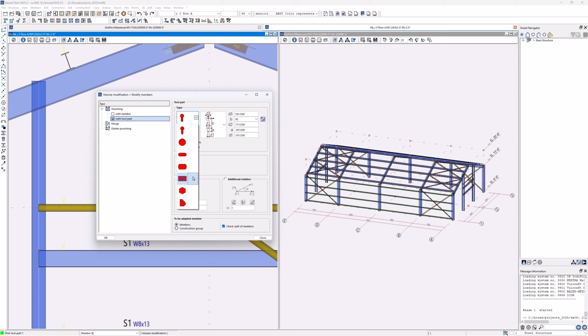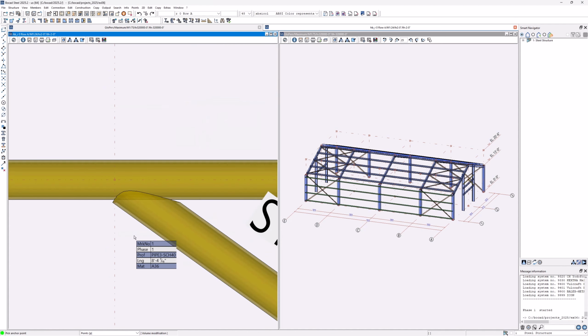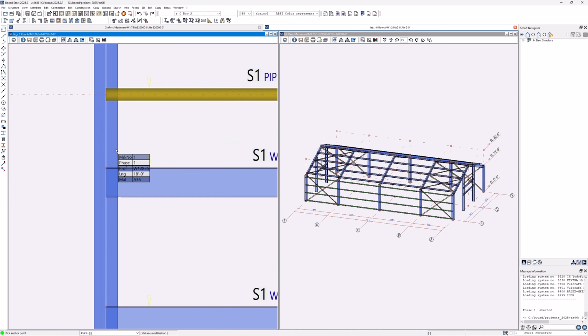Let's create a rectangular hole. It has a length of, let's say, for example, 5 inches, a height of 3 inches. We're going to delete the tool part. It goes through the complete depth. We're at the center of that opening, and we would say, let's come back here. This is the location, enter. This is the element we want to punch through, and we just punch a hole. It doesn't matter whether it's correct or not, or whether it makes much sense in this case. In this case, clearly it doesn't, but it would punch right through the component.